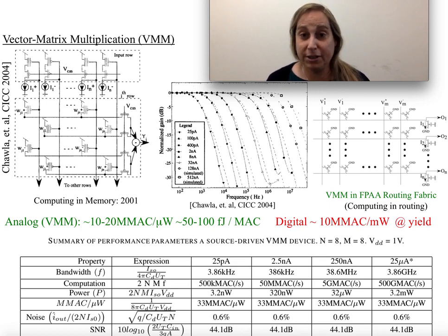Most people would think that's very typical; in fact, it's what we see all the way through most computational operations, for so many reasons. Now the key is to talk about what a vector matrix multiplication is in analog. I want to give a high-level perspective, with a particular focus from both a systems and historical perspective. There's a lot to dig into in terms of how to get multiplication in a single transistor, and we'll go over that briefly.